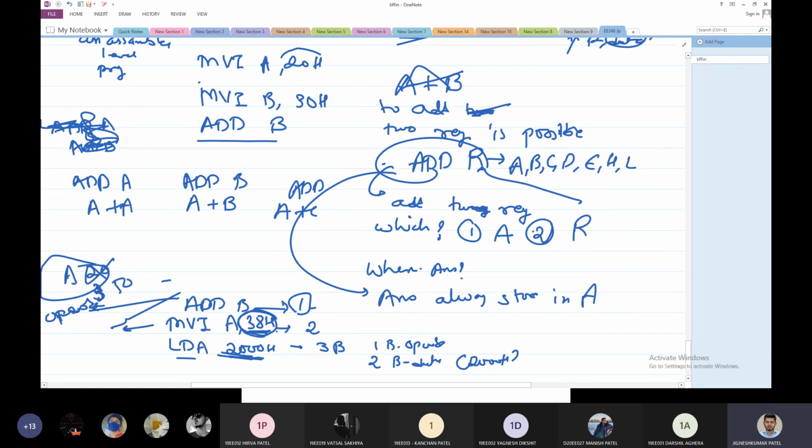If it is 2 byte, there would be opcode fetch plus one more cycle, and if it is 3 byte, opcode fetch plus 2 more cycles. But here the game might change, sometimes it may have 2 or 3 more cycles. But for a single byte instruction, the data is the opcode itself, and the opcode has to be fetched. So a single byte instruction will always have the opcode fetch cycle only. That is the second secret. Okay, keep these two things in mind. Now, any question?